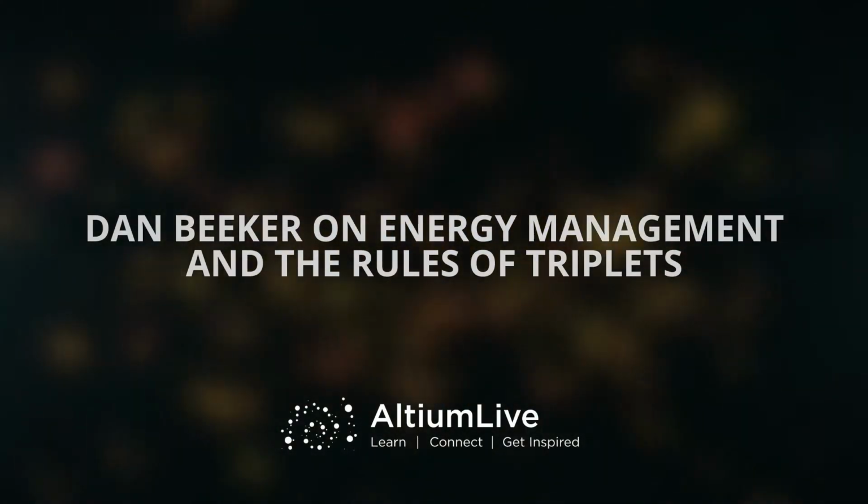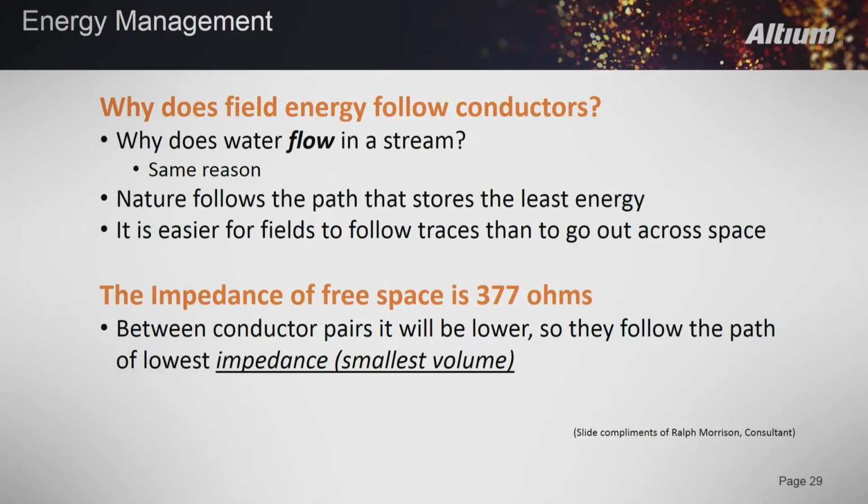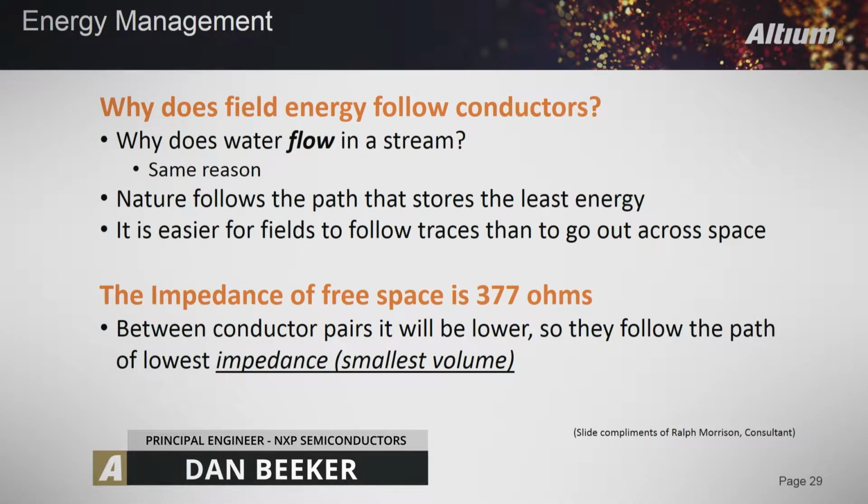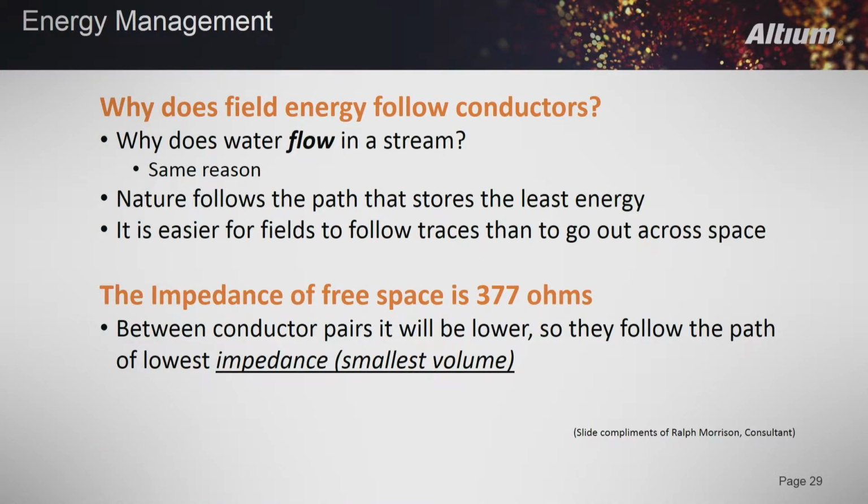The fundamental structure in your boards that you want to build are called transmission lines. Now, a lot of times people hear transmission lines, they instantly go to controlled impedance. That's a special case. A transmission line is any space that's bounded by two conductors. A capacitor we use for storing energy is actually just two conductors separated by a dielectric. For field to exist, you need two conductors separated by a dielectric.